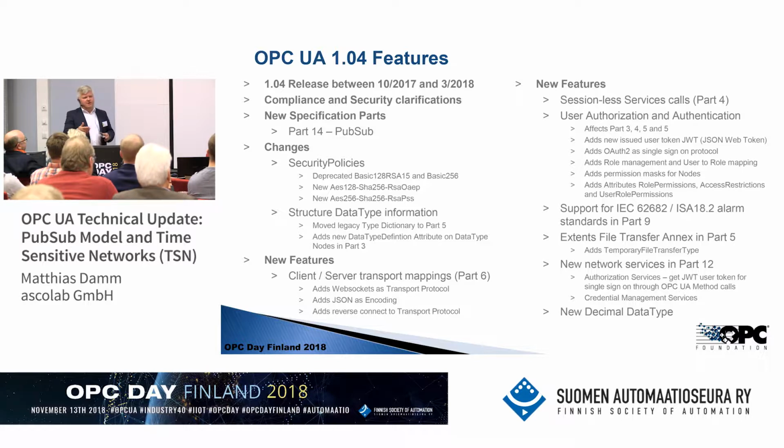So what is a role able to do? Like on a set point, an observer can maybe just read it, and the operator can also write it. And you can configure that now also through standard OPC UA mechanisms. So it was always possible before to manage that with OPC UA, but like the access to it. But now it's also possible to manage the backend. So how you configure the permissions on a node, how you configure roles, how you map roles and permissions together on nodes. So this is now also standardized.